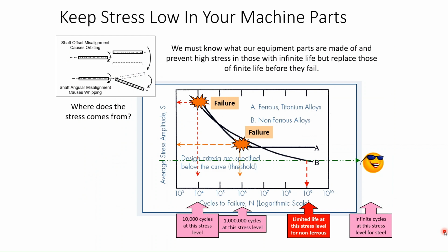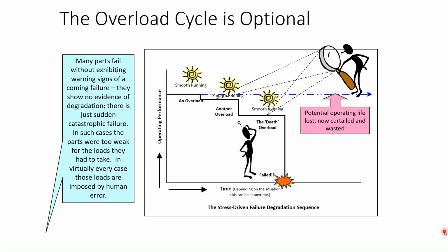Using a factor of safety means the designer intended for the operating stress to be so low that it produced a long, trouble-free service life. We know that parts also fail from being overstressed. This overstress is imposed on the part. Each overstress takes away a portion of the part's strength. When enough overstress accumulates, or there is one large overload incident, the part suddenly fails.